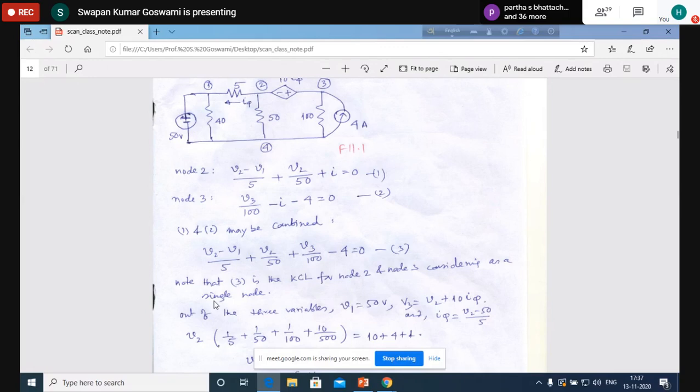That means total current entering into a zone must be equal to total current leaving the zone of the network. Okay, this is the final form you can say. That means total current entering into a node must be equal to the current leaving the node, or the resultant current of a node is zero. Or we can state this in a different way: the resultant current of a zone of the network is always zero. In that case, that zone means considering this part, node 2 and node 3.